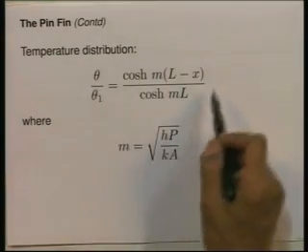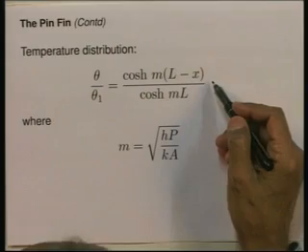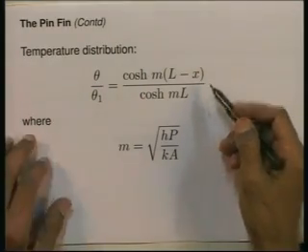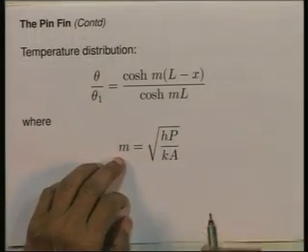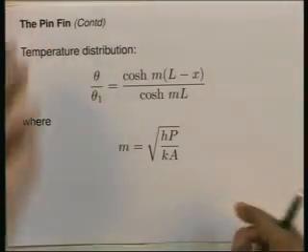That is what we will get for the temperature distribution. It is a very simple solution, because it is a very simple differential equation, where as defined earlier m is nothing but the square root of hp by kA. So, this is the equation that we have got for the temperature distribution, which I sketched for you earlier.